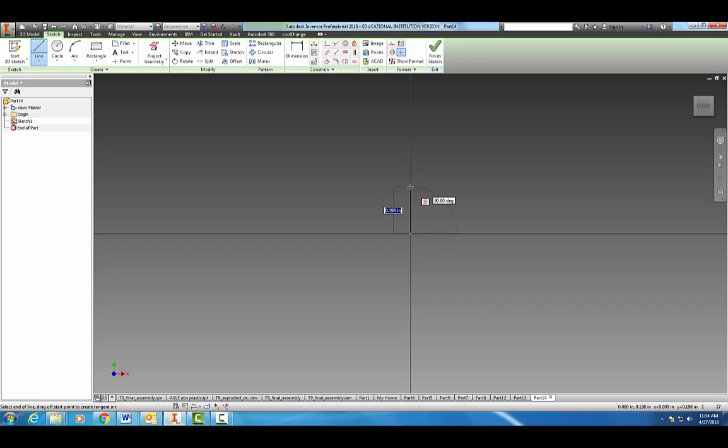So I believe it's about 0.25 height all the way. Let's see here. We're going to come over 1 inch. Now we're going to grab our arc tool. We're going to find that green dot, come down perpendicular to our x-axis here, click, and we're going to do an arc of 0.125. Okay. Good.